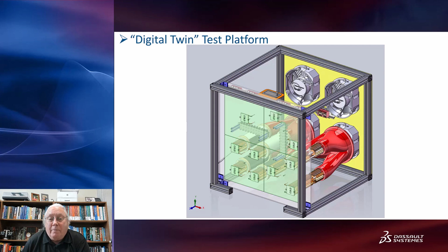There are 4 common fans. Each one of these condensation plates is cooled with one fan, and of course you've got to have ducting that's different depending on how many of these Peltier devices you're cooling, and it shows a couple of them down here. We'll see some more pictures later about what those look like in detail. And it's got heat sinks in here to cool the backside of this thing. So let's go to the next slide and see some more details on this.